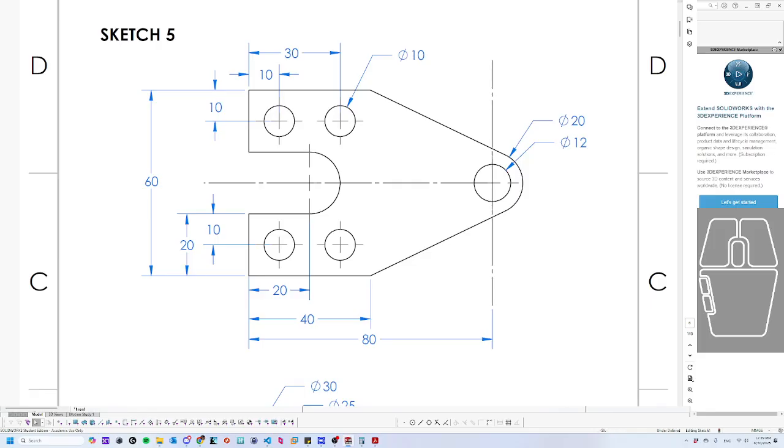That's locked in that side over there. That line doesn't move up and down, which is good. Doesn't move left and right. Doesn't move like that. That moved. So this arc can grow, which means that the thing that's wrong is from here to there. I want these 2 points to be lined up because I want it to be symmetric. And so I can make them vertical. And now my part's fully defined.